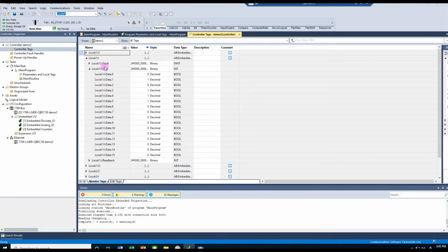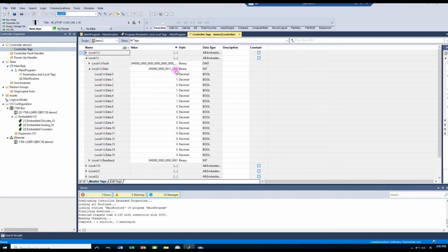And these are the addresses. Okay, so it's made up of 16 bits, so all of the 16 bits combined together, if you look at the number here, this is a 16-bit number. These ones are the ones where the switches are closed, the zeros are where the switches are open. And then it's broken down into binary here. And you can switch it from binary to decimal. Okay, so that's 58 decimal.